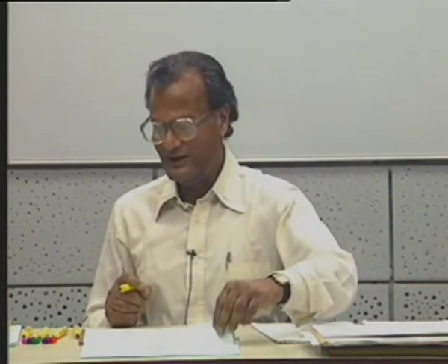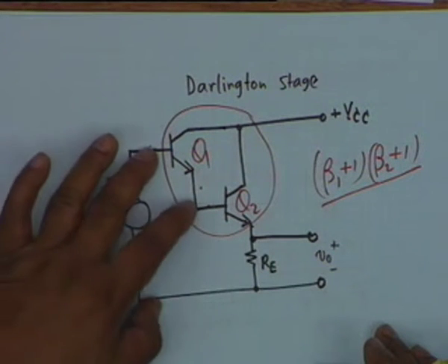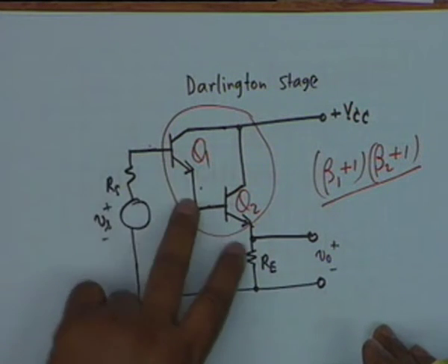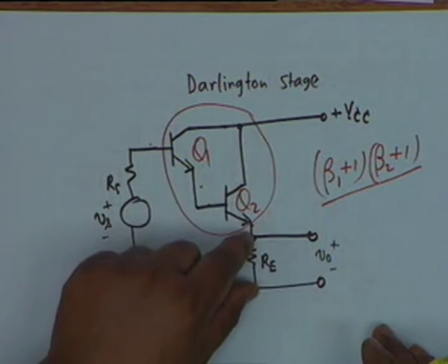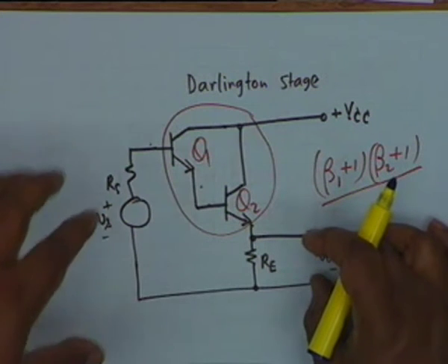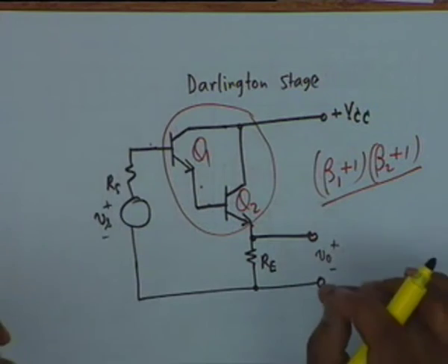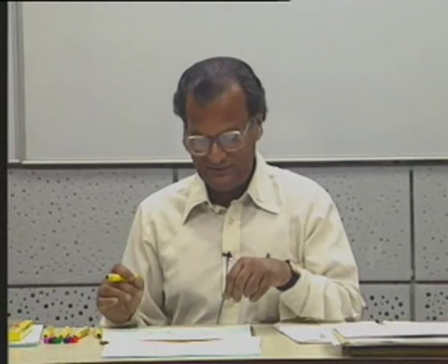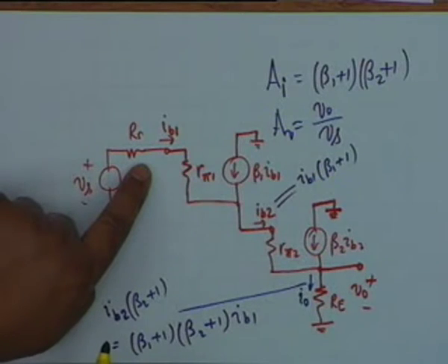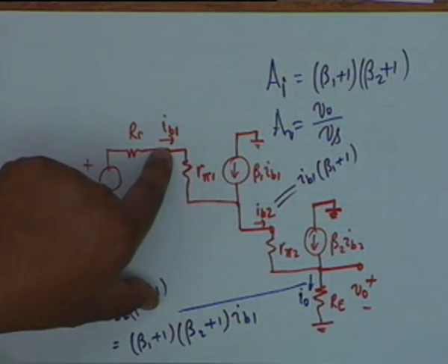If you look at this circuit, this voltage minus VBE1 minus VBE2 is this voltage, and for AC this voltage should be exactly equal to the AC of this voltage, which means that the voltage gain should be equal to 1, but because of RS the voltage gain is slightly less than 1, because what you apply here is not Vs, it is slightly less than Vs.